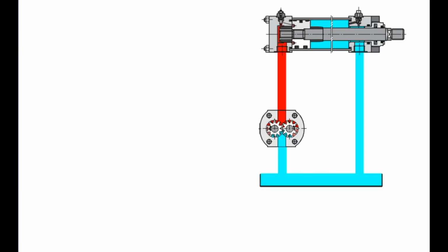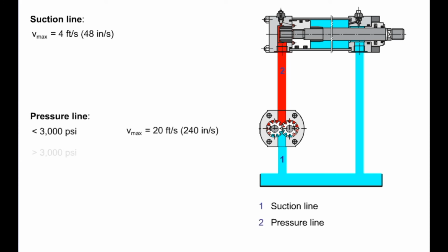In practice, however, there is no need to check mathematically whether the flow will be laminar or turbulent for each and every pipeline. Often the system is designed using experience values. Here you can see some of those values based on experience for the permissible flow velocities, which help to prevent higher pressure losses.